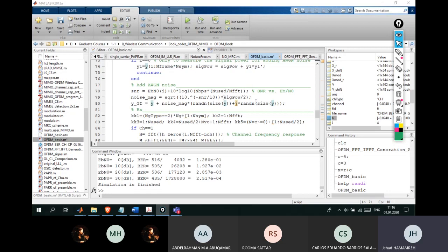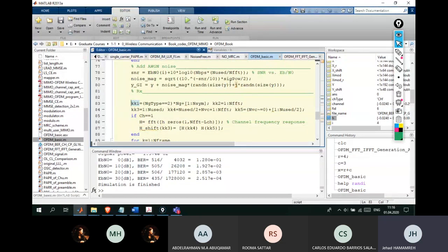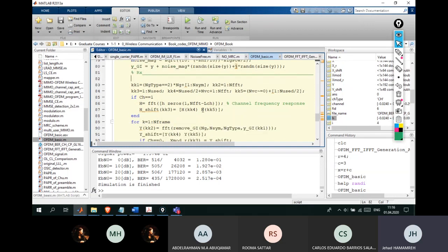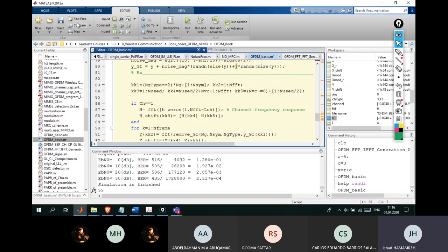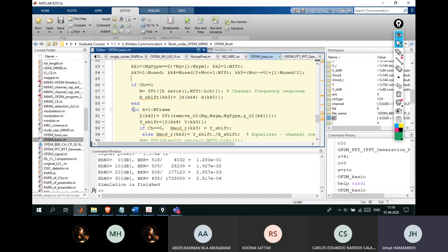You don't need to play with this. You don't have anything to do with noise here. Just leave it as is, because most of your contribution, you don't need to touch this unless you are maybe redefining the power, deactivating additional subcarriers, considering some other parameters. And here, again, resorting the OFDM subcarrier location, doing some shifts and the other things.